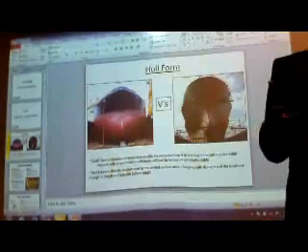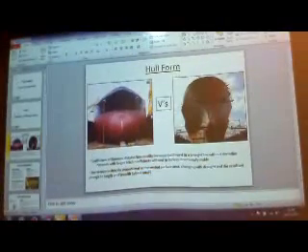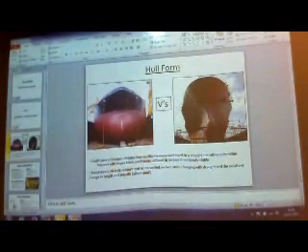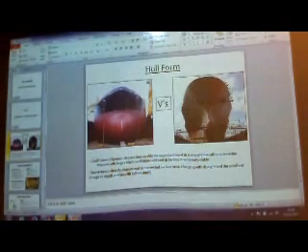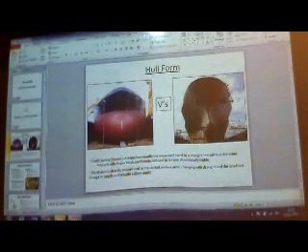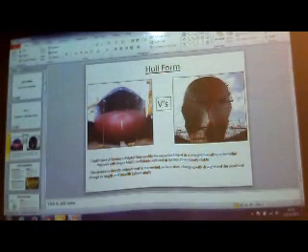So vessels with larger block coefficient. Well, what is block coefficient? Block coefficient is how close a vessel's underwater profile is to a rectangular box. See this ship? It's going to have a very high block coefficient based on how it looks, almost like a box shape. But if I make it more streamlined over here, shave these sharp edges here, shave these sharp edges here, make it more streamlined here, well, then what will happen? The block coefficient will decrease, coefficient of finesse will increase, and this vessel will then suddenly become more directional.